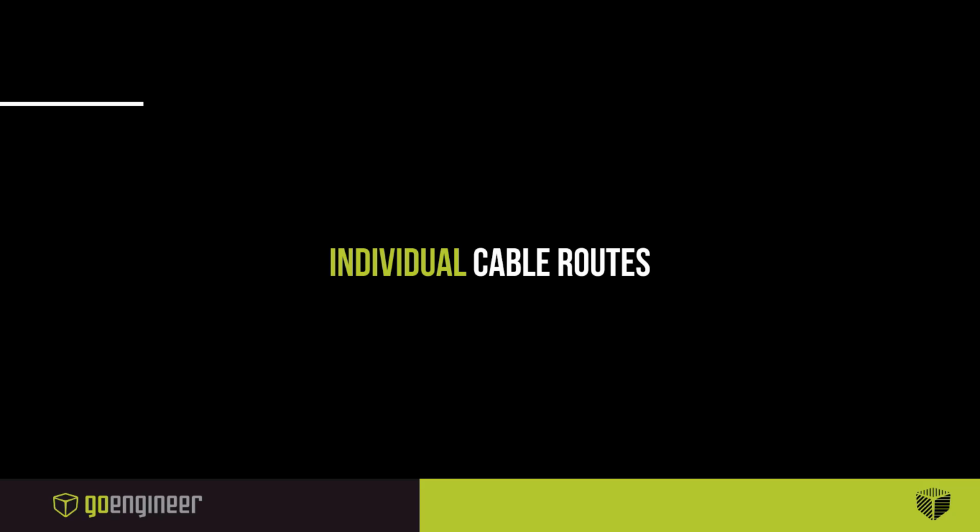Okay, so now we're going to get on to individual cable routes. There's been kind of a shortcoming in the past where, when you have multiple cables in a project and you route them together, they're all in the same routing assembly, which makes it kind of difficult to flatten an individual cable if we need to document that a little more in depth. So what 2021 has allowed is you have the option to say that this cable gets its own routing assembly, which can be individually flattened.